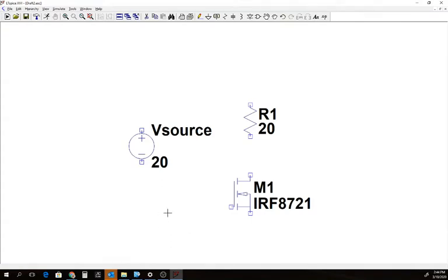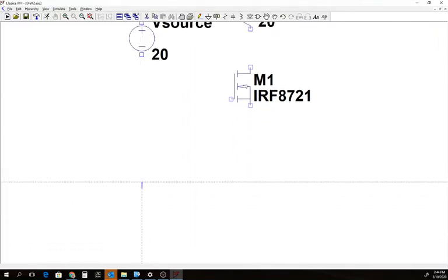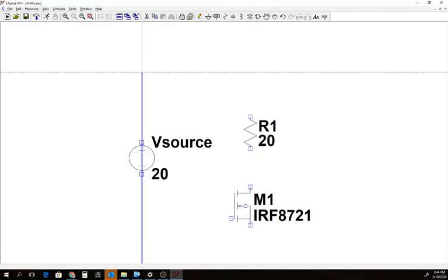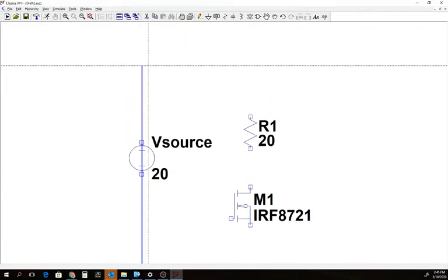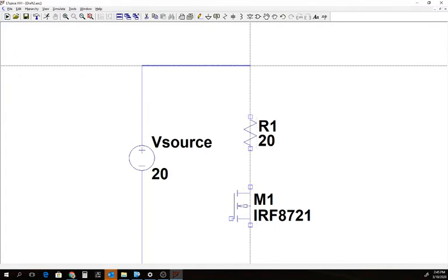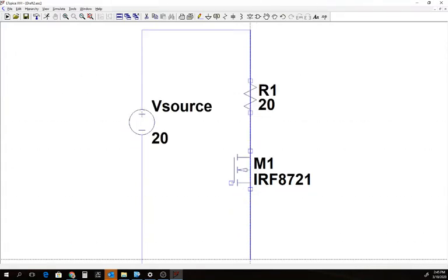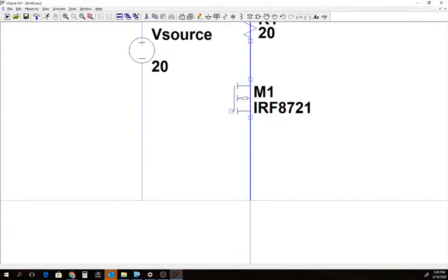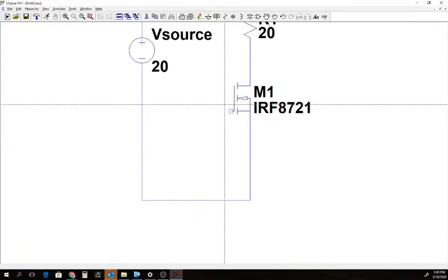So I'm going to wire this circuit up. If you go up here by the pencil, it's your wiring, and you can wire through the device, and it will actually connect it up. And then let me go here, and we're going to wire down through these, and it will actually connect all of them up. And one more, and bring that wire. And so you see it wired it up.